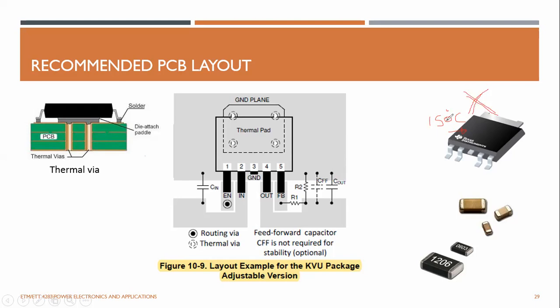So it will collapse when overheated. So selecting the right area for this copper pour and adding a number of thermal vias and heat sinking is the job role of a typical electronics engineer. But that needs more skills. This is out of the scope, but remember, by adding copper pours and thermal vias, you can get rid of the heat and keep your device cooler without exceeding its temperature.